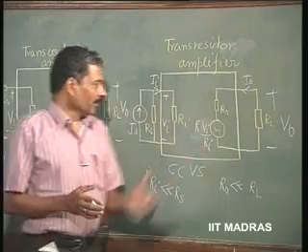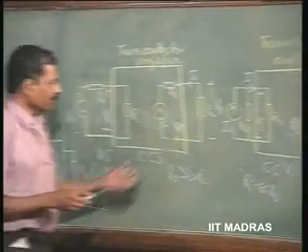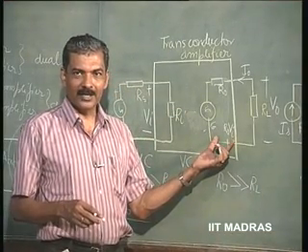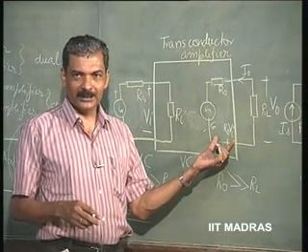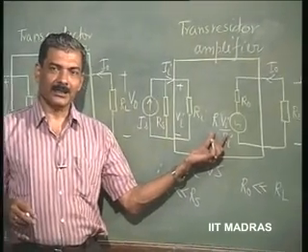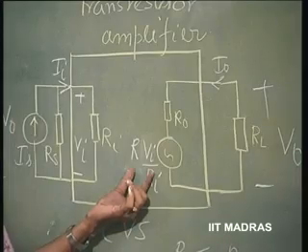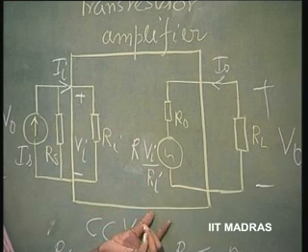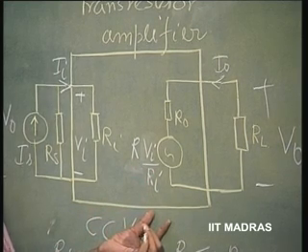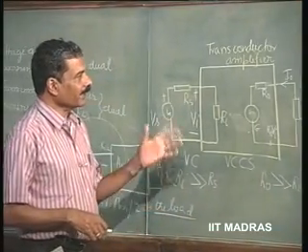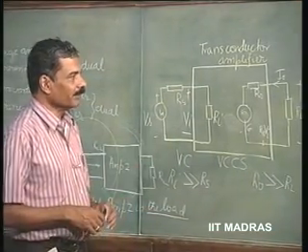So, K in this case has been G times R naught, where G is the transconductance value and R naught is the output resistance of the amplifier, and K here is nothing but R, which is the transresistance, divided by input resistance Ri. So, with this, what all we have discussed in our analysis in earlier situation becomes valid.